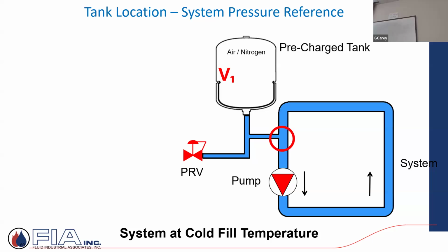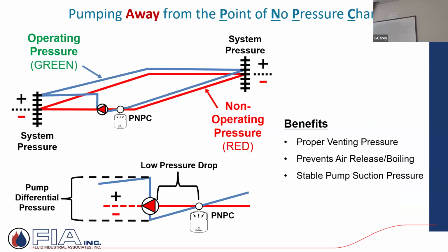Yeah, NPSH. Right, right. We want that positive. We don't want to create cavitation by lowering the available NPSH. Correct. So the point of no pressure change. Yes, yes, yep. No, it still creates the differential. It would create a pressure differential.